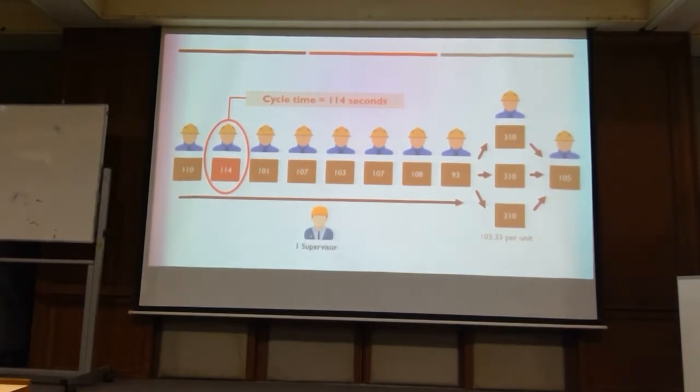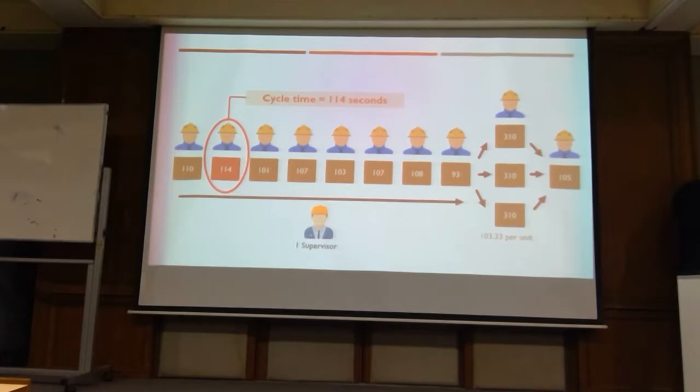So actually, when you do that, you can eliminate that time, 208 seconds. So for station 9, because it's not performed by the operator, you just cut off 208, then you have station number 9 at 102, and just write the thing that you do: 102 is less than 114. So you do it this way.